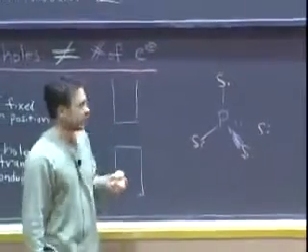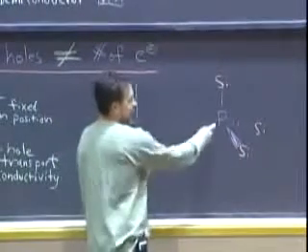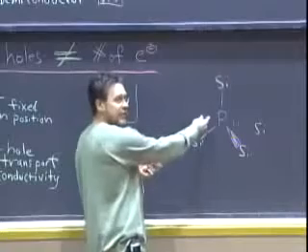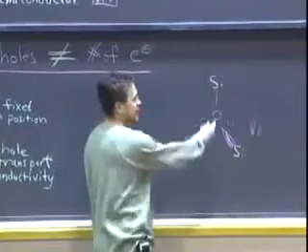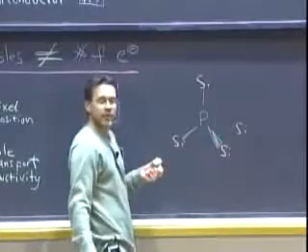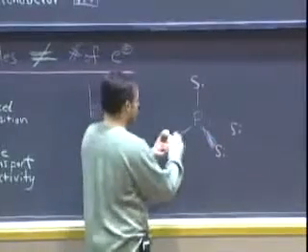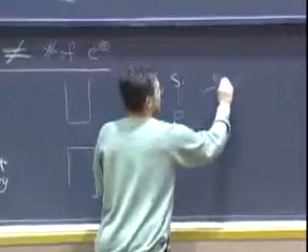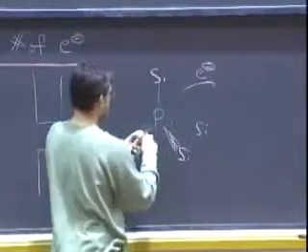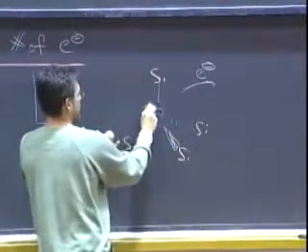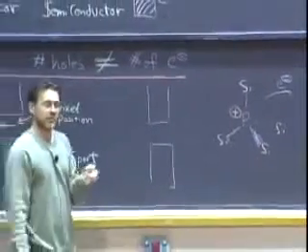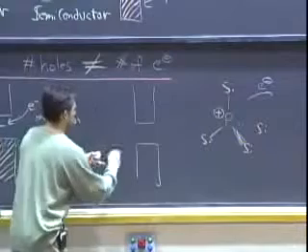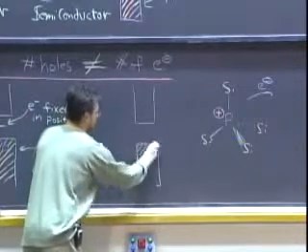silicon semiconductor. And the phosphorus, what happens, it goes in there, it's got an extra electron, it wants to give it up so that it can have just an octet and form these 4 bonds to the 4 silicons. And when it gives up that electron, so electron goes out, that forms a positive charge that is localized and fixed on the phosphorus center in the structure. And so we can represent that as follows,